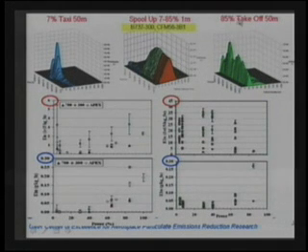Now when you get to 85% power, okay, at 50 meters, you still see this strong feature here, okay? But you also see growing in here a larger component due to the non-volatile soot-like material that's coming from the engine as you increase power. Remember, the mass went up, the number went up as you went up in power, and also the mean diameter went up when you went up in power. So this is here. It's just not making it above the background in these measurements here.